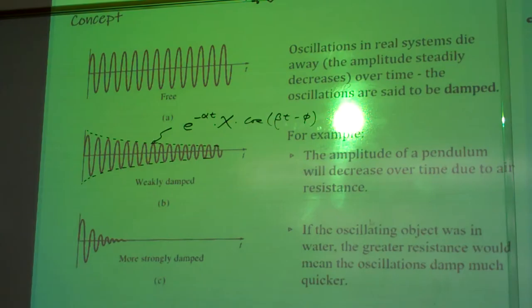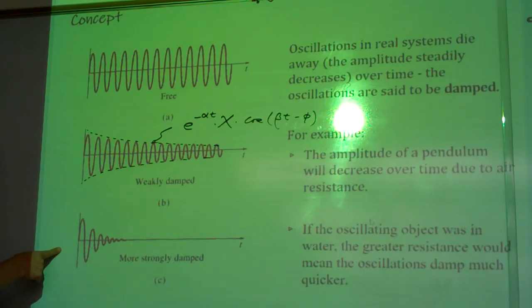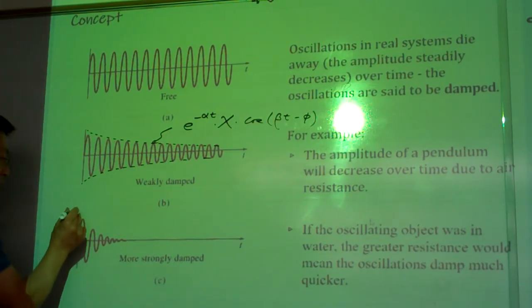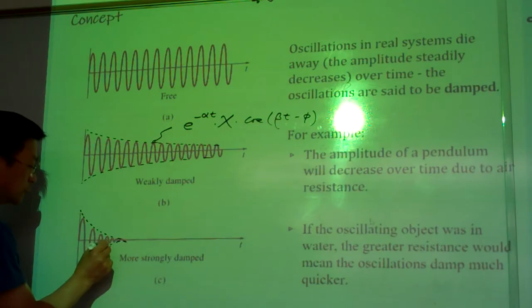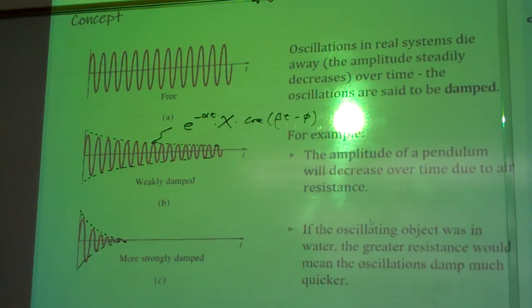Later on we're going to have more quantity relations involving the vibration notation. For this case and this case, they both are damped vibrations. In this one, the magnitude decays quicker, indicating this system has more energy dissipated. So right away, before getting to the numbers, you can see this one has a larger damping than the other. That's a good feeling to pick up before we get into the numbers.